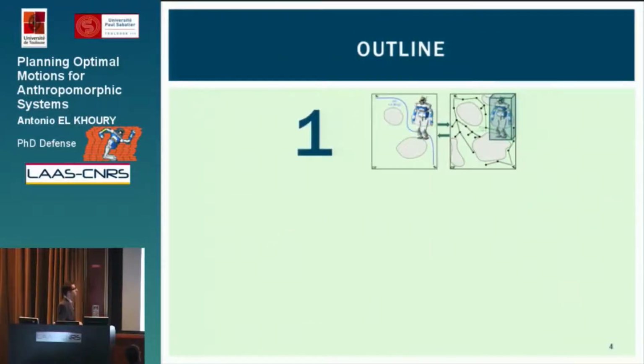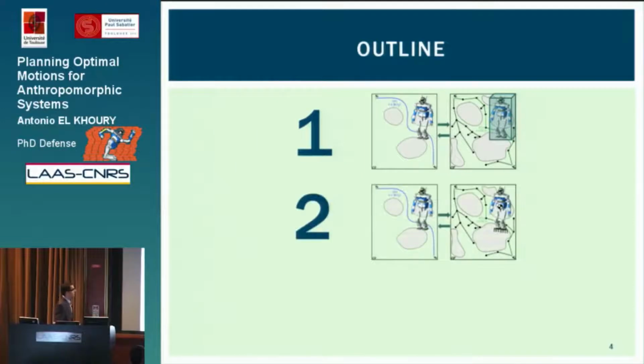So in the first contribution, I developed a path optimization technique when we are using the bounding box approach for a walking humanoid robot on a flat surface. In the second contribution, I do not consider a bounding box, but the whole body geometry of the robot. But we consider a specific kind of constraint, mainly static balance constraints, where we just look at how the center of mass is moving, and we consider in this case that we have a fixed set of contact points.